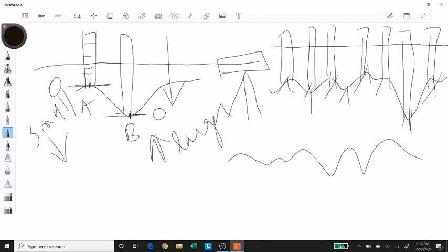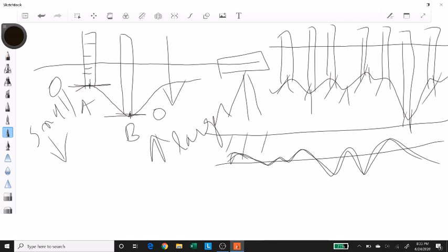and not just the profile. You can use it to find out the water carrying capacity of a valley. You can find out a number of things. Let's say you want to build a road in a terrain that looks like this, and if you have this profile of the land, you can decide on the grade of the road and the elevation of the road, because you have different options. I can build my road over here while the ground is over here. So that means I'll have to fill up this entire area.